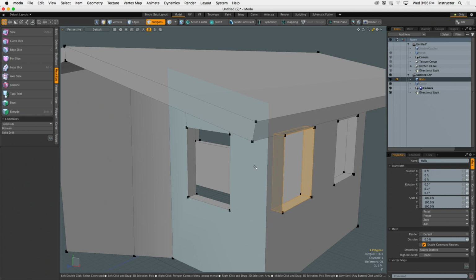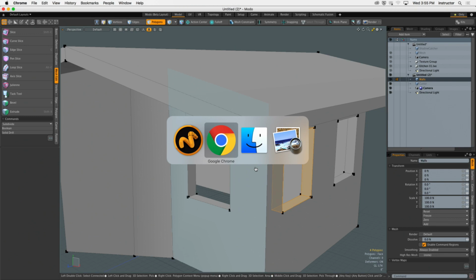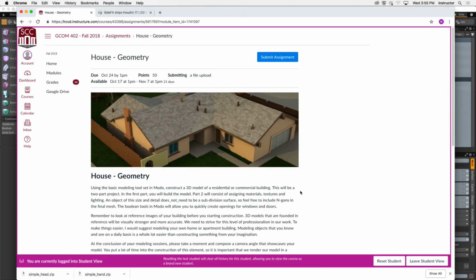But then I said, okay, show me the render of your finished project. And of course, they went to a render shot that looked honestly not too dissimilar to this, okay? And they didn't see it at all, right? It was just hours and hours and hours of energy on their front door. And what that translated into was basically just a cube and a cylinder to make the doorknob itself. I felt so bad for them, but it looks great, right? So we got to be careful. We got to pick and choose. We don't want to put a ton of geometric detail in something we're not going to see. But windows and trims, if you look at this picture here, you can see the windows. You can see the trim. That's good stuff to add into our stuff. Yeah?